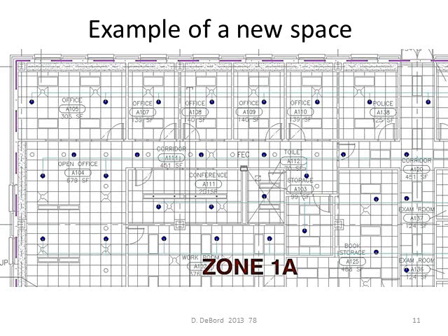For a new building, we see a ceiling grid, we see diffusers, the lights are 2x4, the ceiling grid is 2x2, and sometimes there are downlights that are open circles. And here the fire protection piping is showing up as a green color, not very heavy in this case. And then we see some solid dots that represent the sprinkler heads.